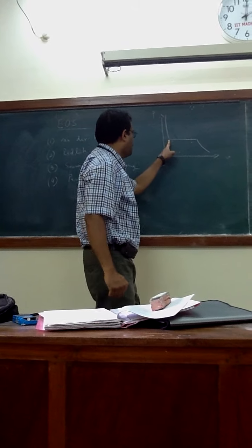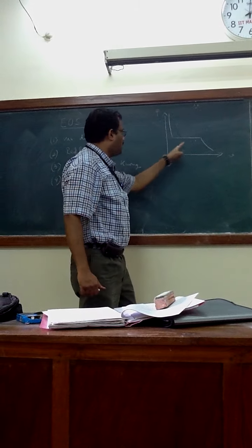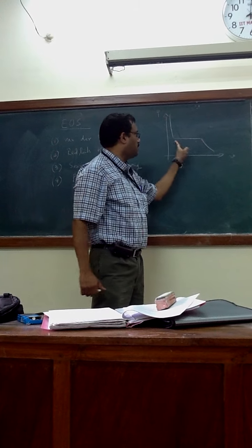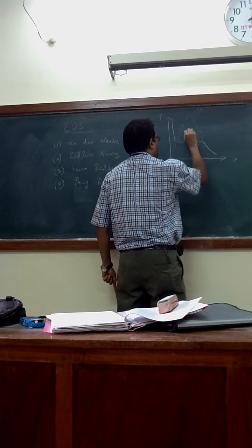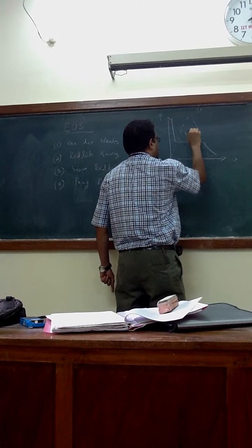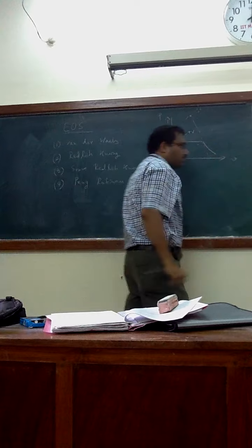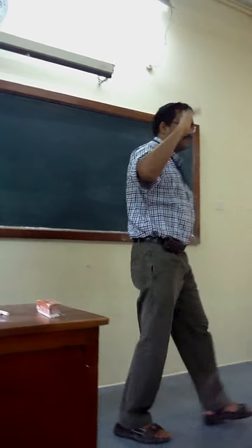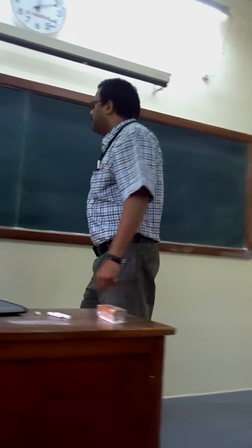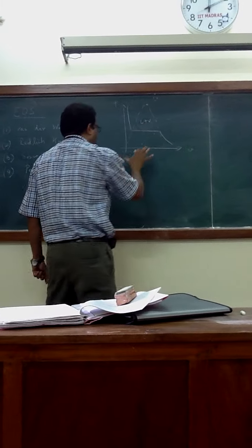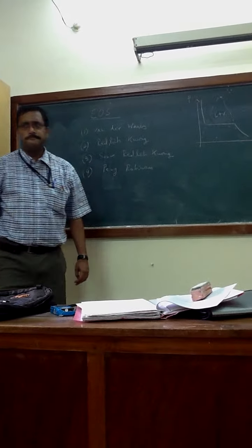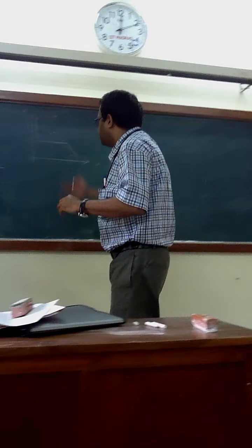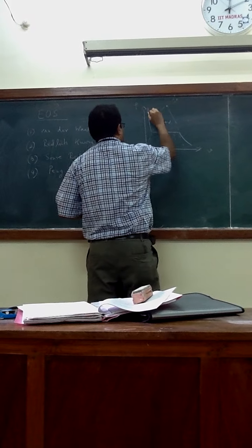Physics will say this is the liquid part, this is the saturated liquid part, the saturated vapor part, and between them is the liquid plus vapor mixture zone. And this is the last point where the liquid exists, beyond that is gas. So this is the generalized perspective of the cubic equation of state. This could be valid, and this is from physics.